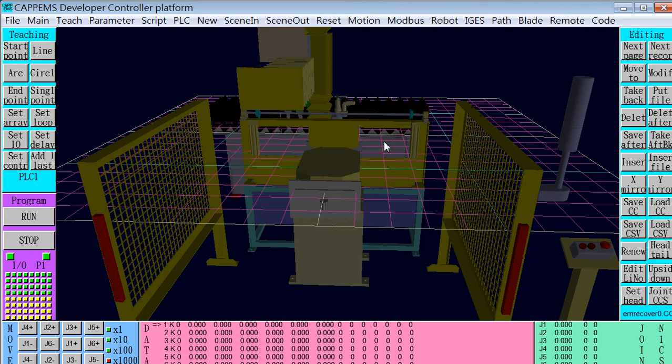After the window is up, the program will run to clean one side of the component, and then turn the B axis component 180 degrees and clean the opposite side, with axis positions to eject and remove the stones inside the shaft.